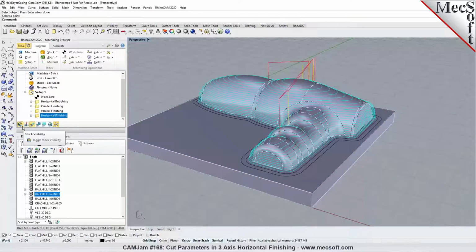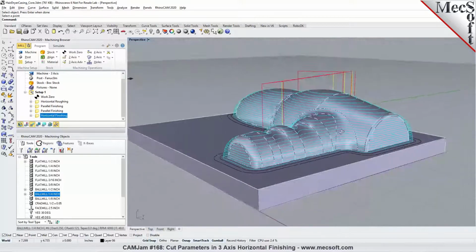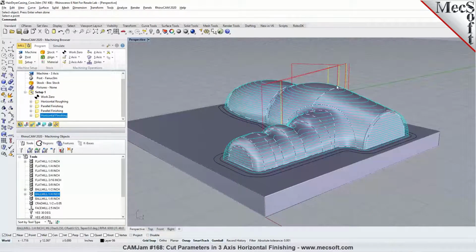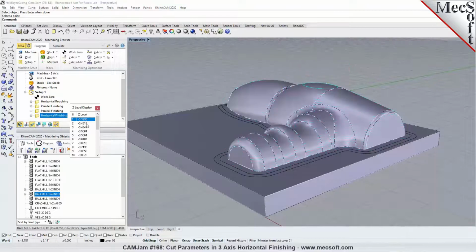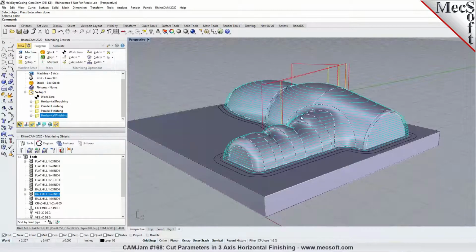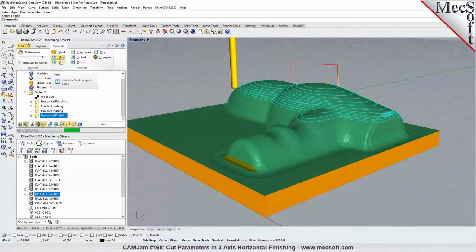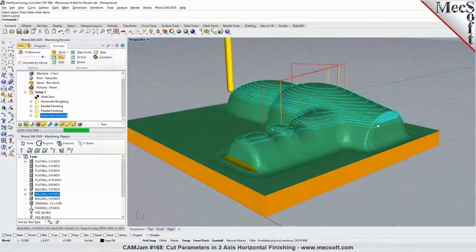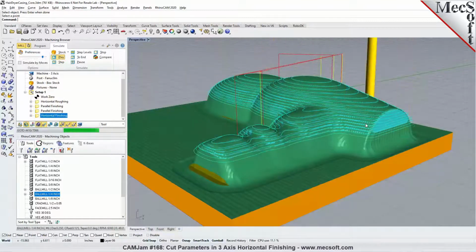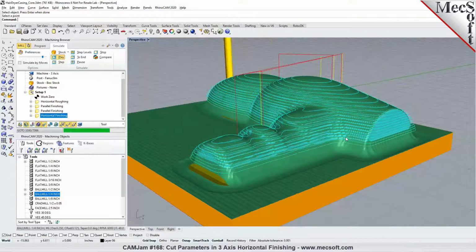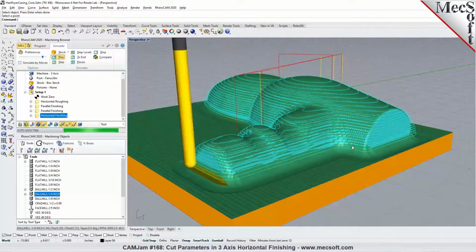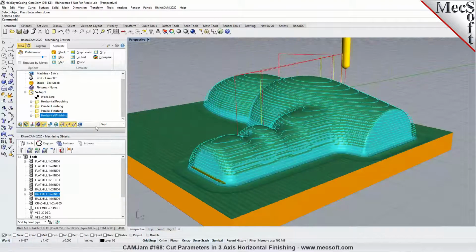This will result in the horizontal finishing toolpath. You're noticing here the toolpath generator is known as horizontal, or also called Z-level finishing, where it's generated in constant Z levels. I'm stepping through the Z-level display, and as you can see, the toolpath displays in levels. So this is a good technique to program steep areas in your 3D models, and this will take care of cleaning up all of the scalloping that was left in the steeper sections on this particular core mold.